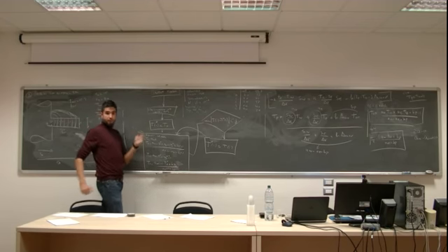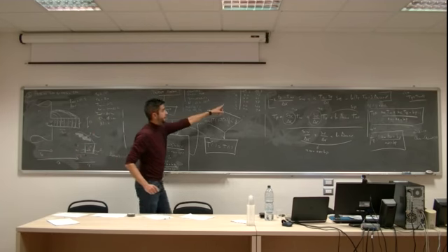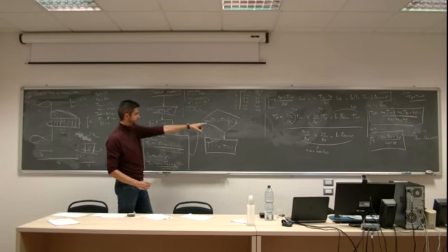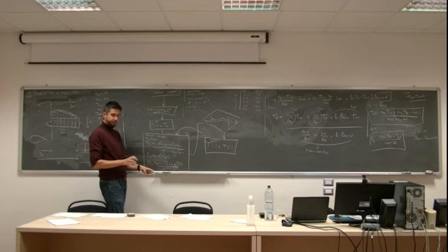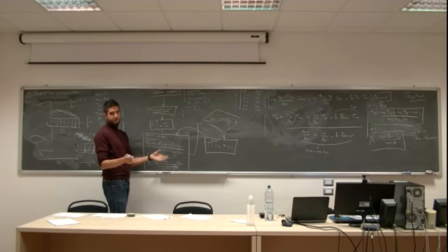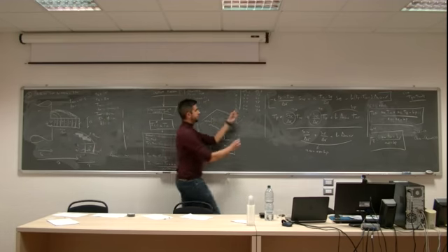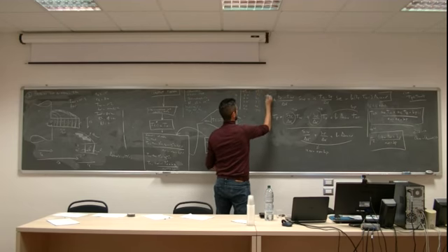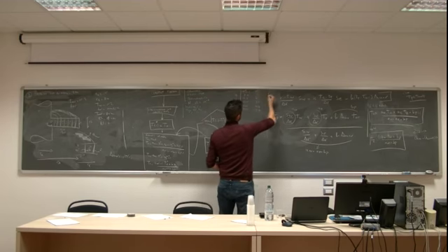Because I didn't have any clue, I started with 70. After passing through the whole set of equations, I got a map of temperature. Is what I assumed the same as what I got? No, it's not the same. So now do the same process, but assuming the map that we have calculated. Now this will be assumed, and I will get another iteration.